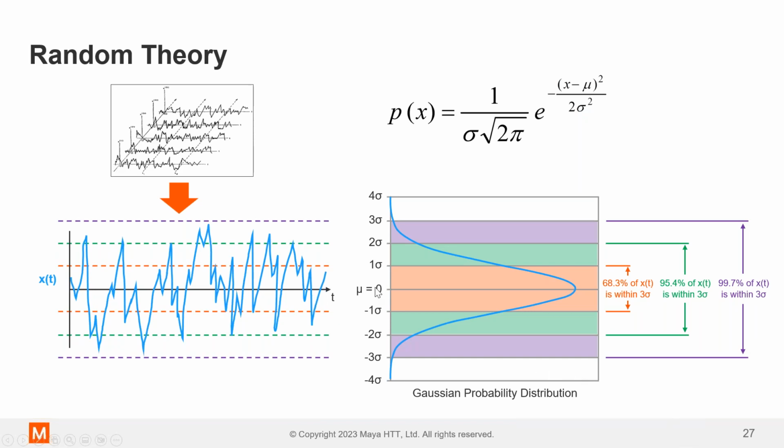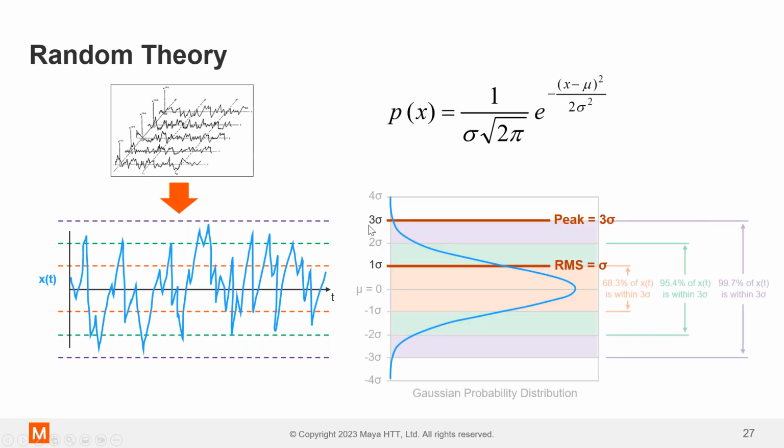And so your RMS value is going to be the 1 sigma value, and your peak value, your peak stress that you use to determine if your component yields or fails, is often going to be 3 sigma, 3 times that RMS. And there we go here.